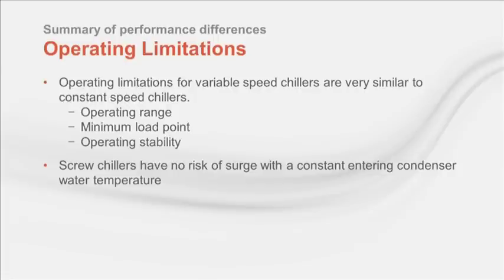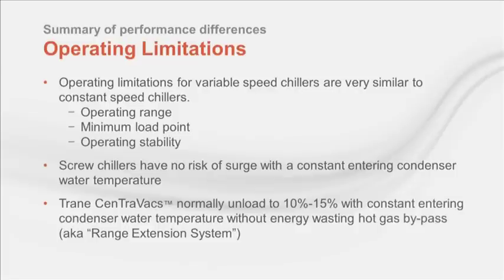Higher than designed condensing conditions can result in bearing loads or discharge refrigerant temperatures that can damage the compressor. But under normal operation, it does avoid the surge concern. The surge resistance of a centrifugal compressor varies greatly depending on the compressor design and selection.